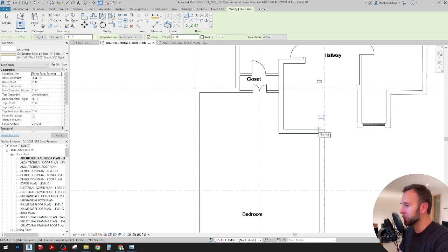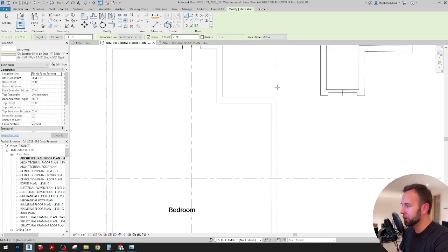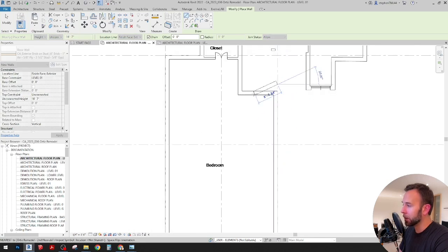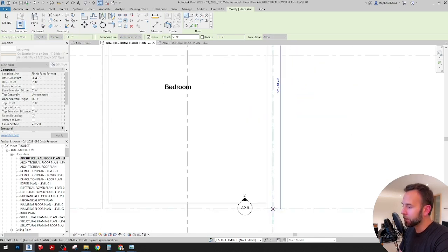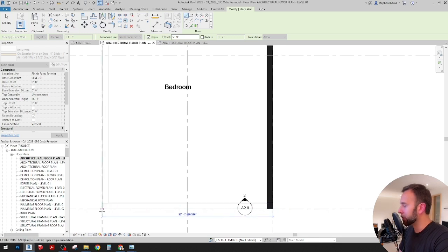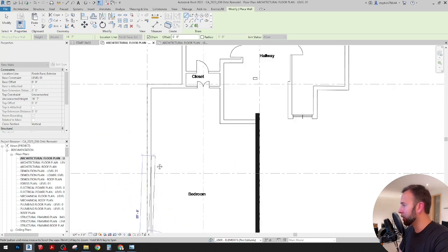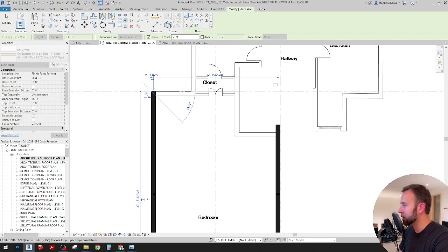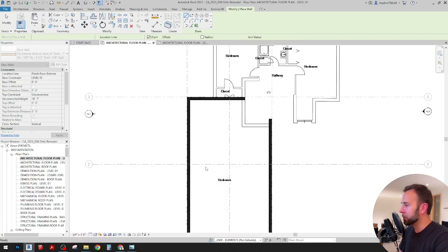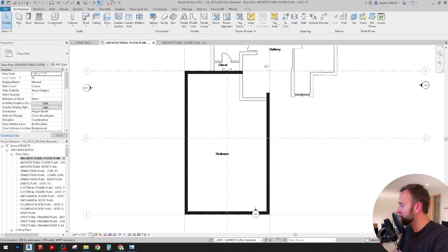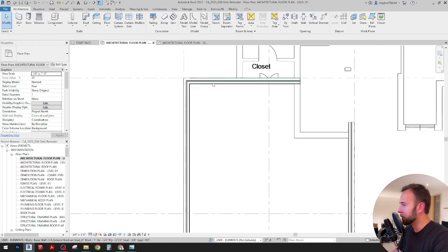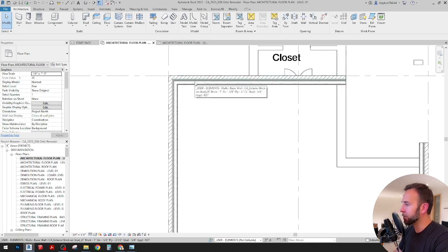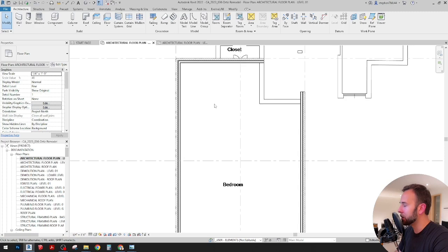But again, make sure that when you're modeling this, you're using the grid lines and not necessarily the surveyed lines. Sometimes it might not make as much of a difference more than other times, like in this case, but it's just something to be aware of. So I just want to get the perimeter of the building here, and let's make sure that our exterior was in fact pointing outward, and yes.